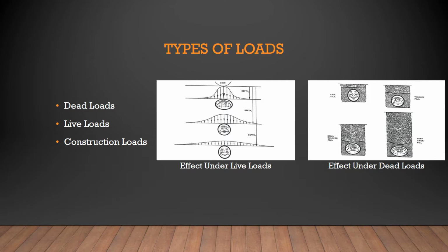Live loads are temporary loads that act on the underground pipes that can change in both location and magnitude. Typically, live loads are caused by traffic and other moving loads. Unlike dead loads, live loads felt by underground utility pipes decrease with increasing depth of the pipe. Because the load from the backfill soil layer is taken into account with the dead load, the live load is modeled as a load that dissipates as a function of depth from the load source.